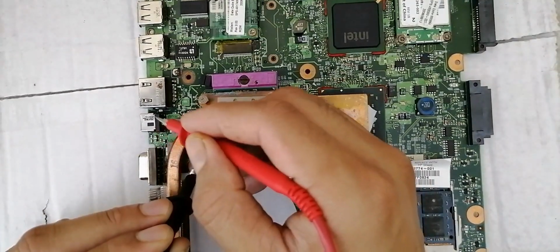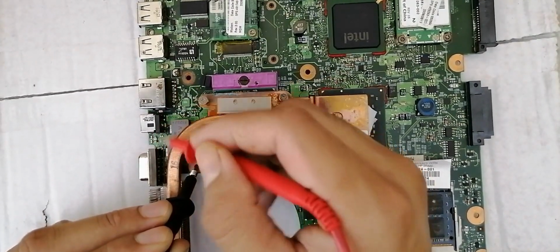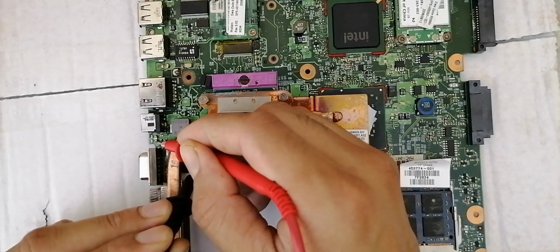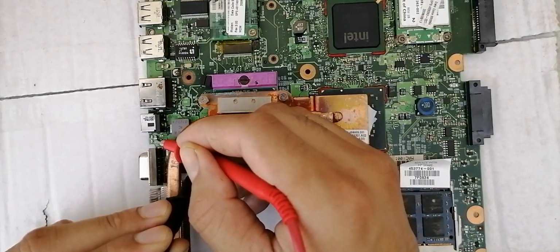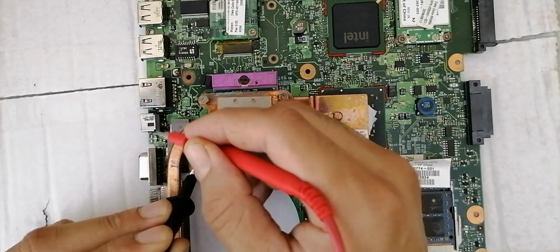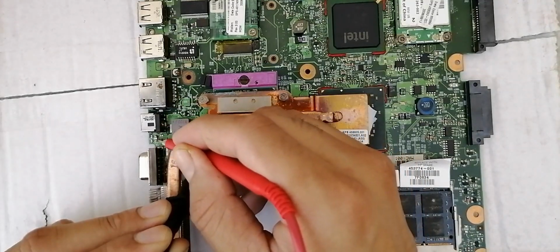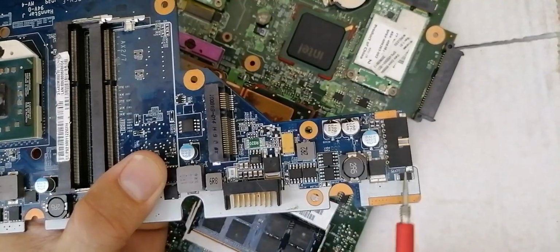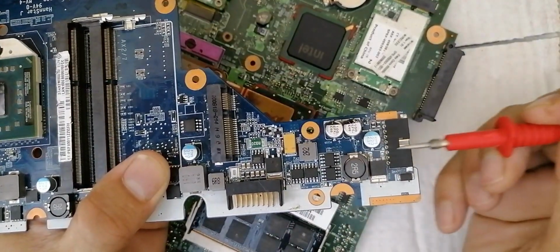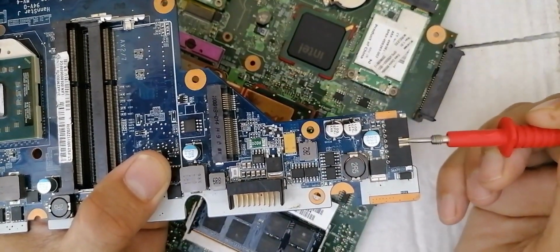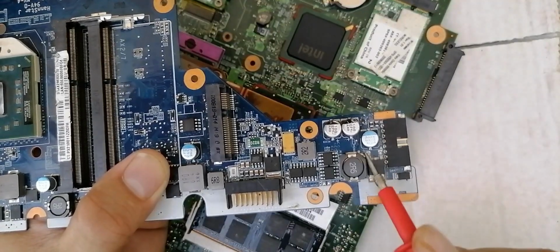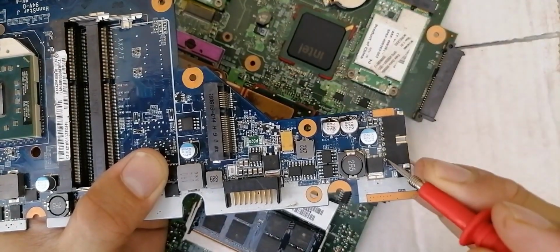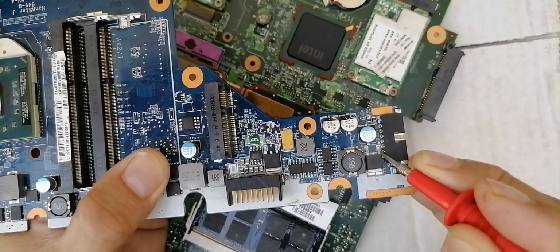Okay, in the first component around the power jack, for example, the inductor or fuse. If you find the 19 volt here, for this motherboard, you should check, for example, this component. This is basically an inductor. You should find 19 volt here. But for this motherboard, for example, this is the power jack. Here we have the connector for the power jack. You should check this MOSFET. You should find basically 19 volt here in the source of this MOSFET.